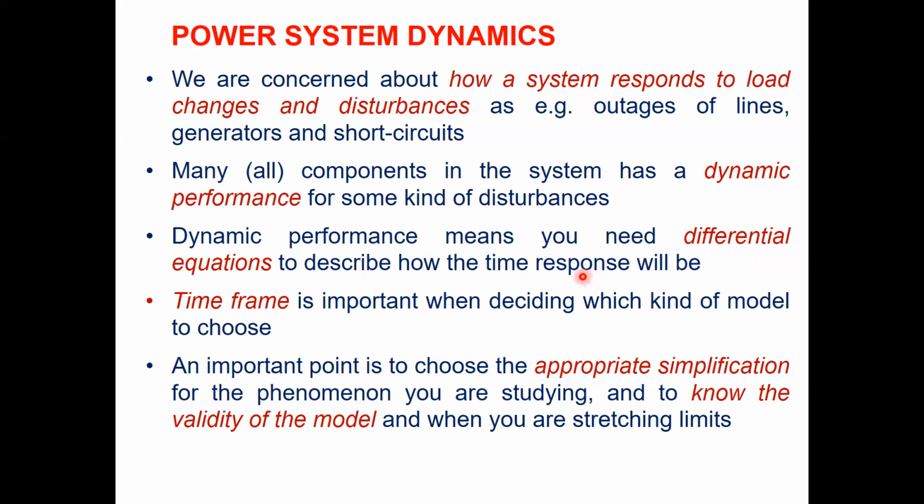That means how the generator, turbine, excitation system, controller, or governor is going to change its behavior, what the dynamic variation of the states will be for each of these components. They are modeled in terms of differential equations, and they will tell you the response in the time domain.